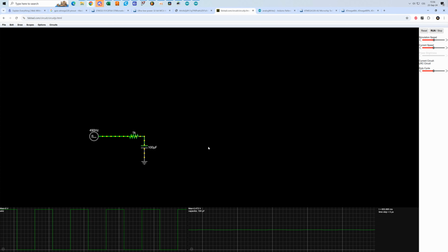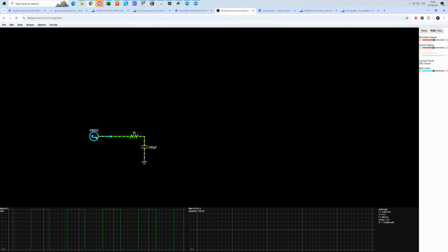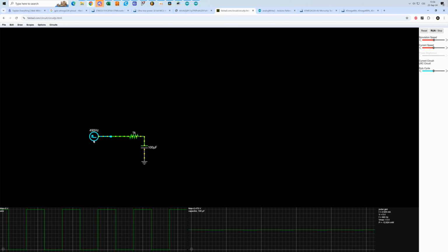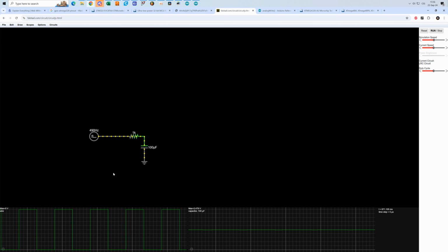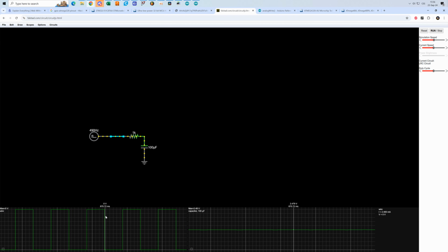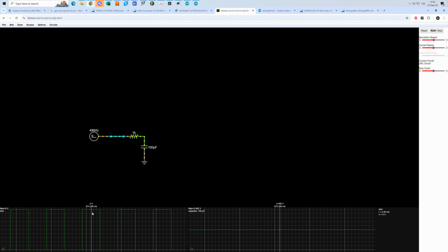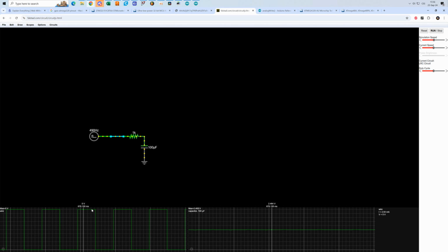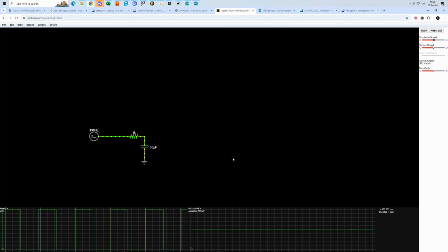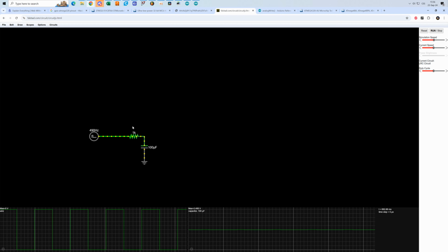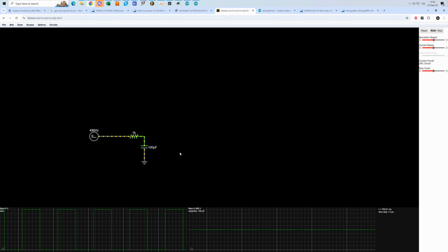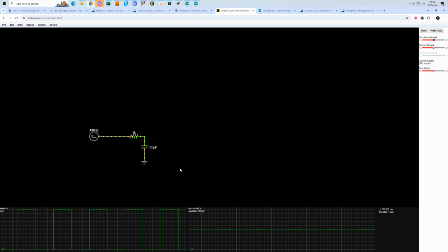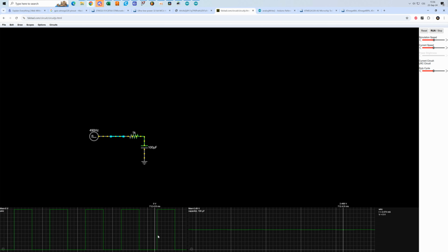So this is just a simulation. You can see here we have the PWM source. It's just a square wave source voltage. We can see it here. These are the pulses. It's either 0 or 5 volts, logic high or logic low. And what we did here is that we added a low pass circuit, which is just a low pass filter from a resistor and a capacitor. And what this circuit does is that it averages this square wave.